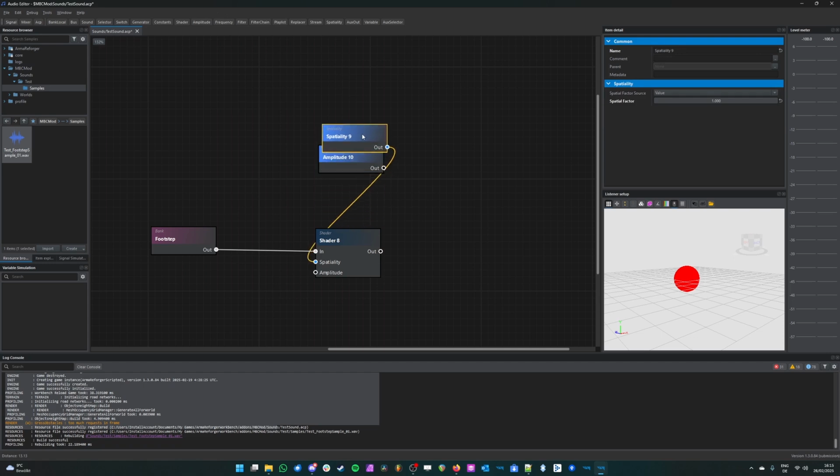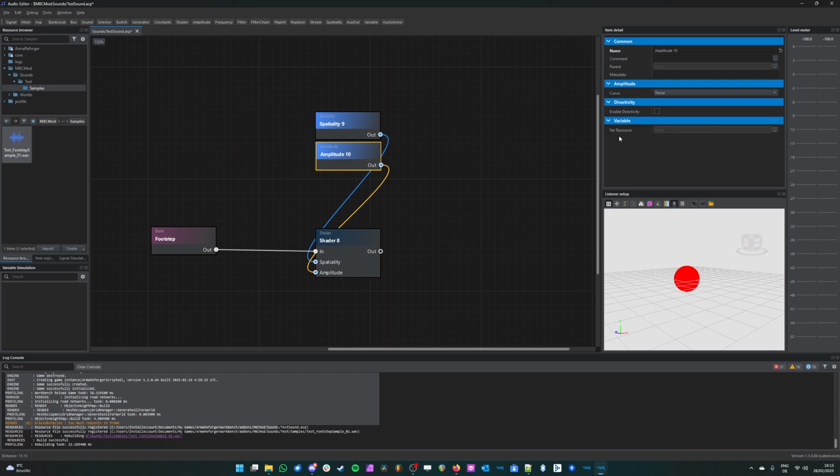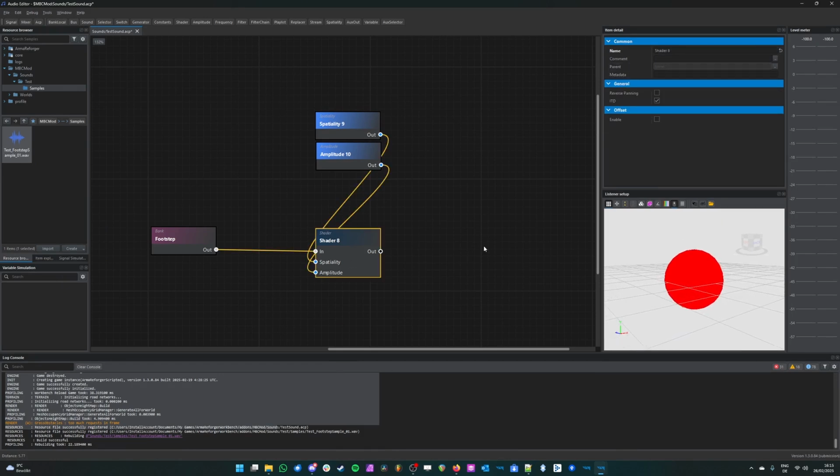Moving on, the next input that we have here is the amplitude. There it is. And the amplitude really is nothing else but the volume falloff over distance. So by default, nothing would happen because there's not much set here. We can set a very simple one through a curve. Now we have an inner range, meaning within this range, the audible volume will not change at all. Let's leave it at 1 meter. And we have an outer range. And once this outer range is reached, the sound will not be audible at all. And I hope you can see it at the bottom left here. We can see the distance. So you always know how far away we are from the current sound source. And if we move away from this little orb here now in the listener window, you can hear that indeed it is now spatialized and gets quieter over distance.